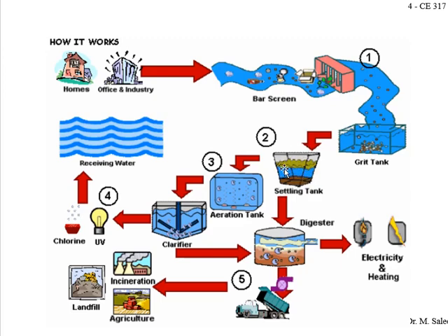So here, what we do is keep this water in the tank and leave it for a few hours. Then most of the solids will settle down because of gravity, and from the top we can take the clearer water. Up till here it is called the primary treatment, right? And from the next step it is called the secondary treatment, which is generally the biological treatment.